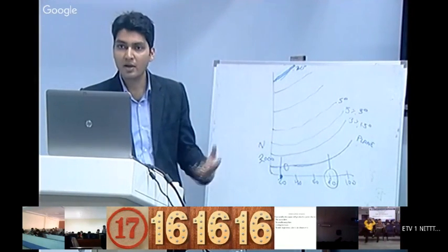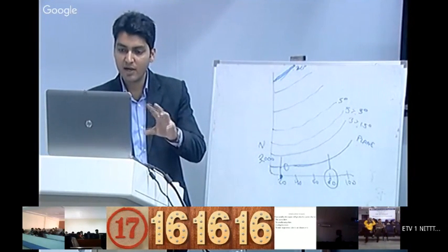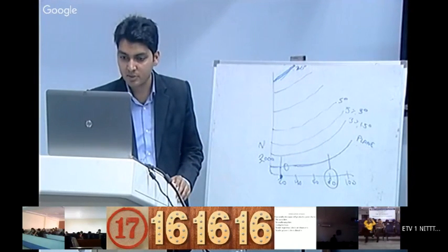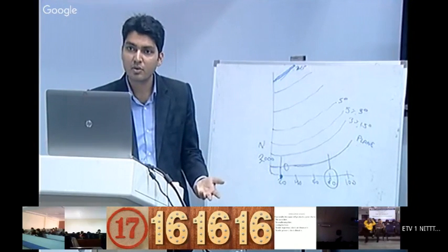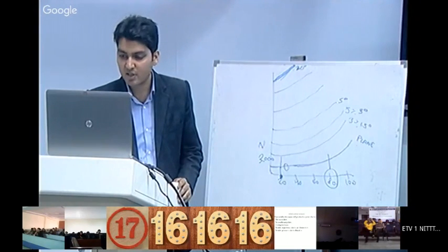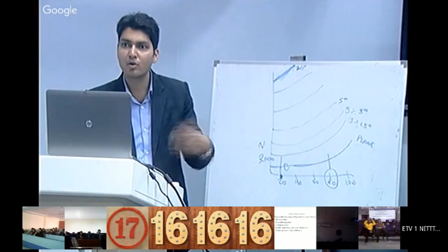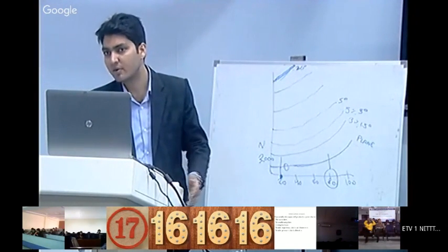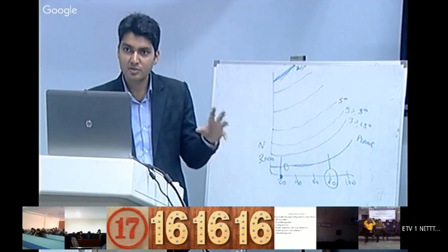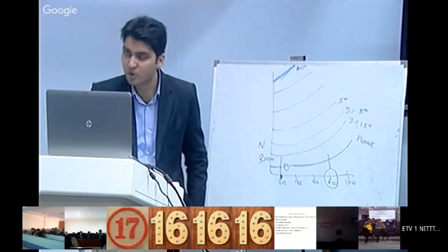When we install an air cleaner in the engine, for CFD purposes, we find a depression in the air inlet. So that also contributes to losses. Air inlet pressure due to altitude: when we increase our vehicle gradient levels, then the air pressure decreases. When the air pressure decreases, the turbo and other requirements of the engine differ. Then the exhaust back pressure: when we are testing the engine on a test bed, we do not put any exhaust system on the engine.